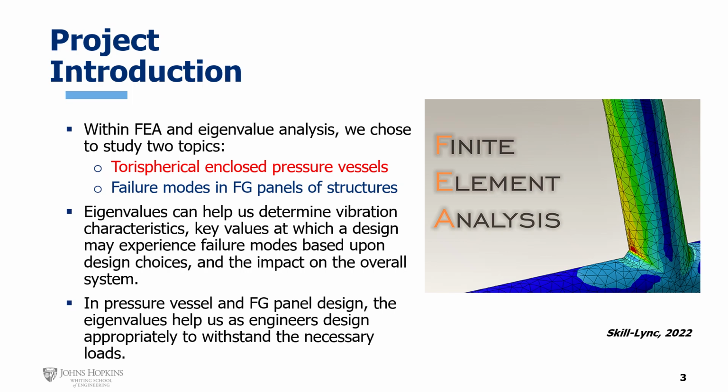So part of that project, these pressure vessels are seen everywhere. I mean, they're critical components in different engineering worlds, power generation, aerospace, defense. They're often used in high pressure scenarios, so the possibility of buckling is pretty common. Large stresses incur on these vessels themselves, so it's generating lots of points of failure, which, as we know, we can use FEA to mitigate and try to figure out where these points will be and maybe change our design to eliminate that possibility. And those failure points come from these critical eigenvalues, which we'll see in the equations in the next slide.